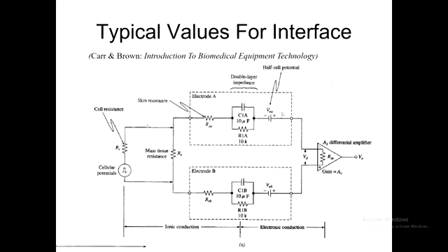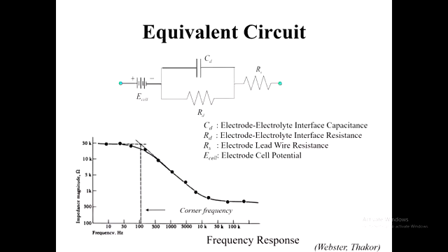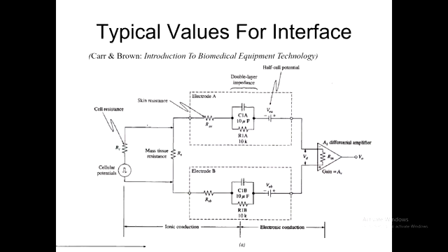So why don't we think of these DC sources now? They're off the scale, aren't they? In terms of this here, they're way off the scale. They're way over to minus infinity frequency-wise. So we can regard those voltage sources as short circuits, not worry about their DC behaviour, because in reality we expect these two guys to cancel each other out for the most part.